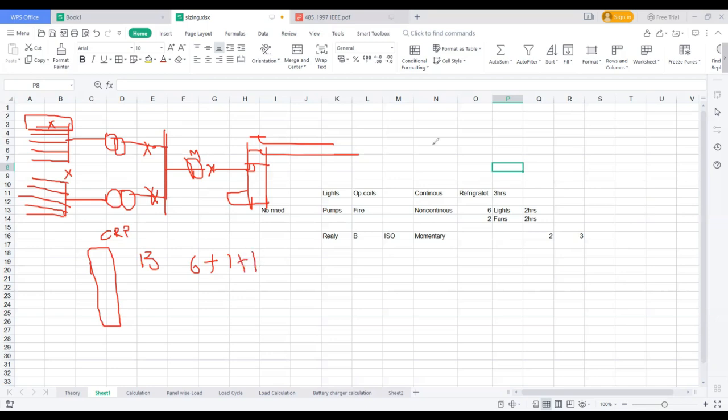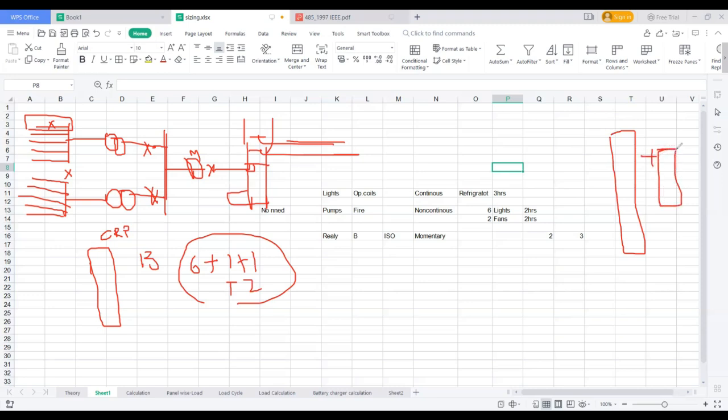generally. And if the 220 kV line is having two panels, again we'll add two. So these are the number of panels, depending upon the combination of the relays and the controlling part of your substation. So for these panels, I have to list out all the emergency essential loads, relays, operating coils. And apart from this, if I want to give this battery also for the SAS, and also for some lights, it's upon your choice.